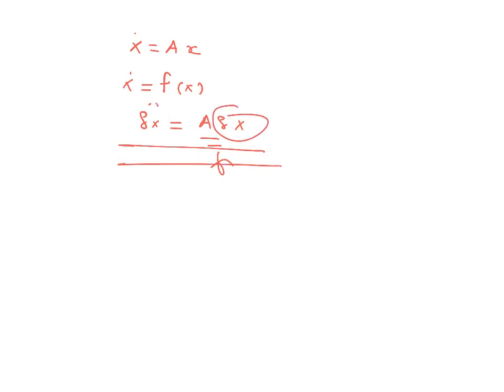So now what are we doing? These pictures were for the actual x dot equals A x, right? But now we are talking about a nonlinear system, f of x, right? So you can always linearize this. That is delta x dot equals A delta x, right? So basically what I'm saying is you will exhibit the same behavior near the equilibrium. If it is a linear system, it doesn't matter where you are; it will exactly follow the same thing. But now we are talking about deviation from the equilibrium point. Delta x is the deviation from the equilibrium point.